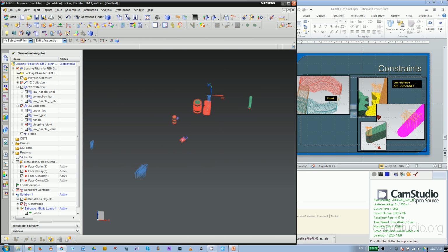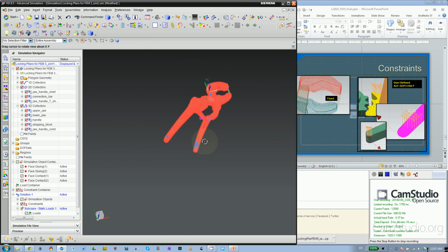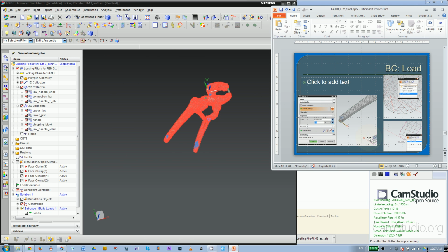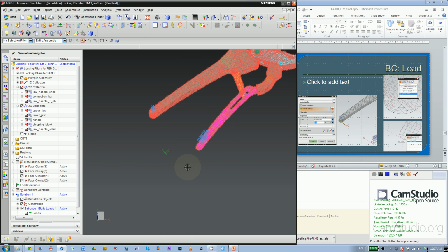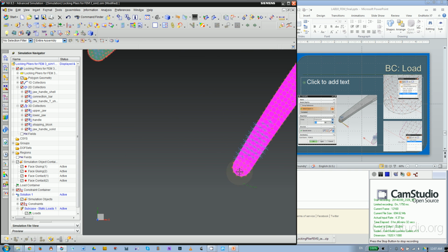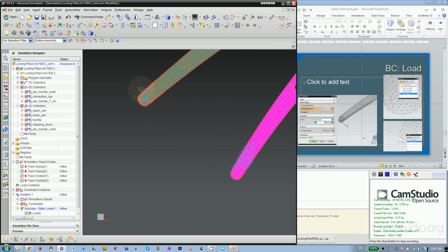Alright, now the last step, force. We're gonna squeeze this handle using 10 pounds of force. So we're gonna apply force on this node as well as one node somewhere here, in the middle of this 3D mesh.